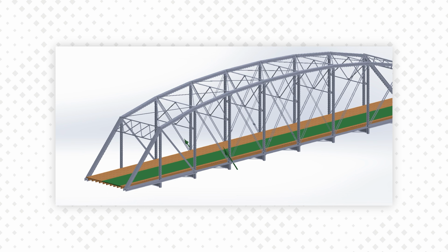They eventually deliver a vertical resultant to the abutment. Because the forces are eccentric to the abutments, they create a bending moment, which is resisted by tension in the bottom chords and compression in the top. In Module 4, we will use statics to understand this further.